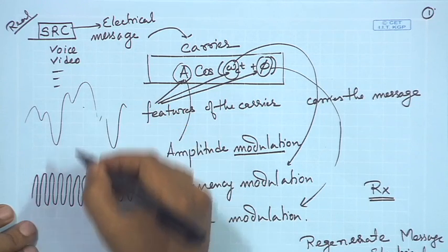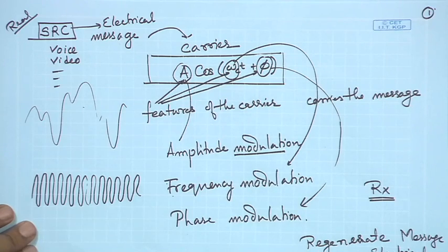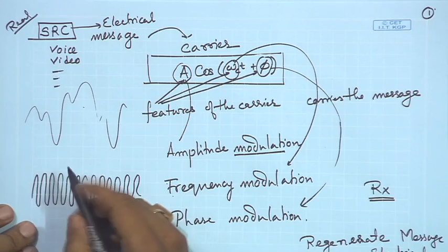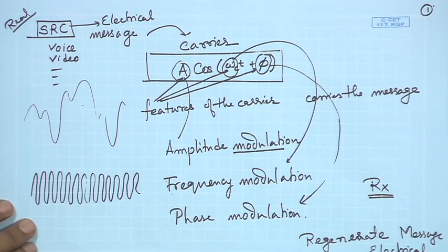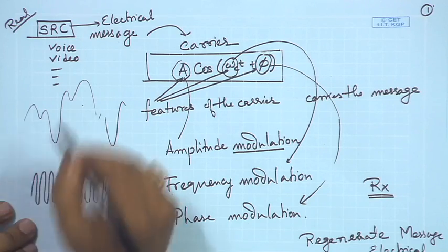When this is imposed onto this, if we talk about amplitude modulation, then you would apply some scaling factor so that it does not cause a reverse swing. You can still do it, but generally you would not allow the signal to go to the opposite phase within the modulation period, and you would limit the amount of modulation.